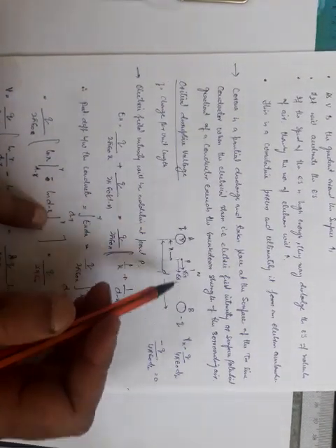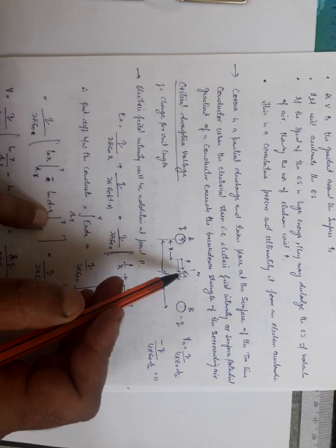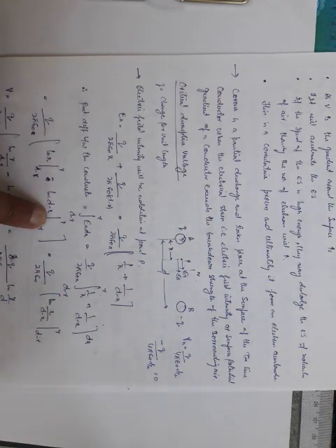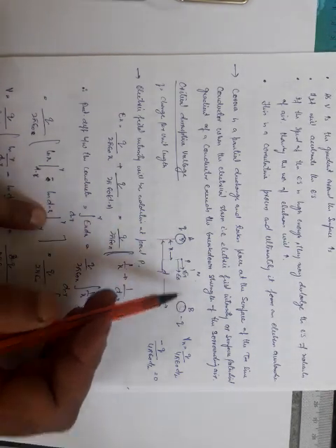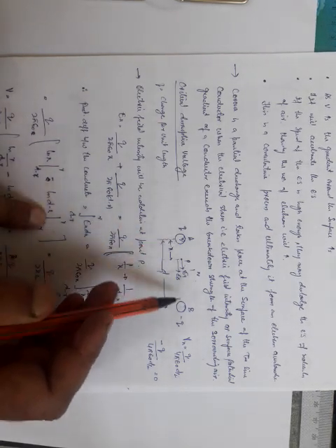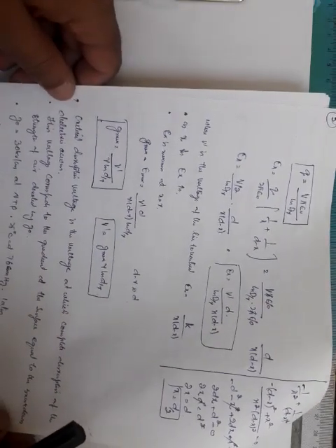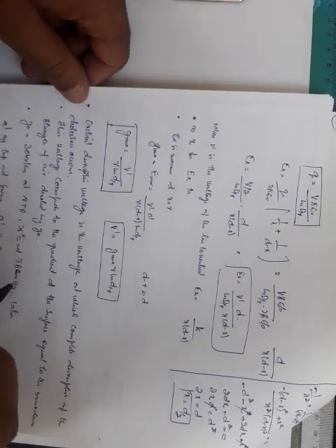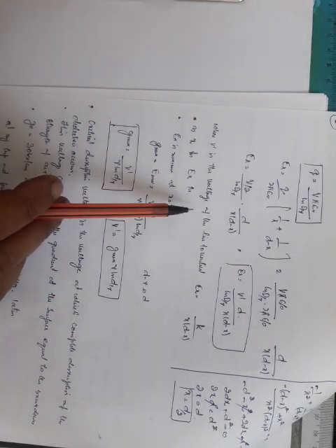V is the voltage between A and B, and at point N, since we have to calculate the phase voltage, that will be VAN or VBN, that will be definitely VAB by 2, that's V by 2. So this V dash by 2 will be the phase voltage, V dash, between conductor A, let us say, and neutral point, where V dash is the voltage of the line to neutral.